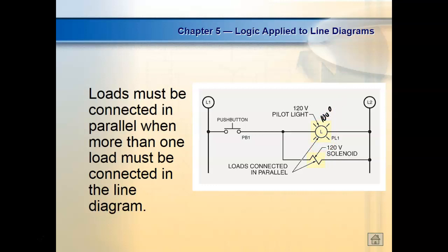You understand that? So the only 2 types of circuits we have in motor controls are a single load series circuit, which I'll call a basic circuit so as not to confuse y'all, and parallel circuits. And that's it. And how many loads can I put into parallel? Well, I can put as many as L1 and L2 will handle without blowing a fuse or burning up, right? Everybody understand that? No multi-load series circuits in motor controls. And that's also true of PLCs, by the way. Everybody understand that rule?